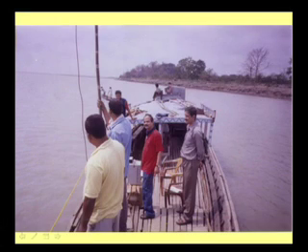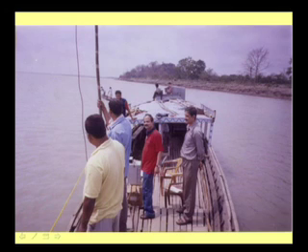Say here this stick is carrying a sensor at the bottom, it is not seen here, and this wire is connected to this sensor which is placed at the bottom, and then this is connected to this flow meter. Say we are anchoring our boat, and then we can see what the flow velocity of this river is at a particular depth. That way we can keep on measuring.